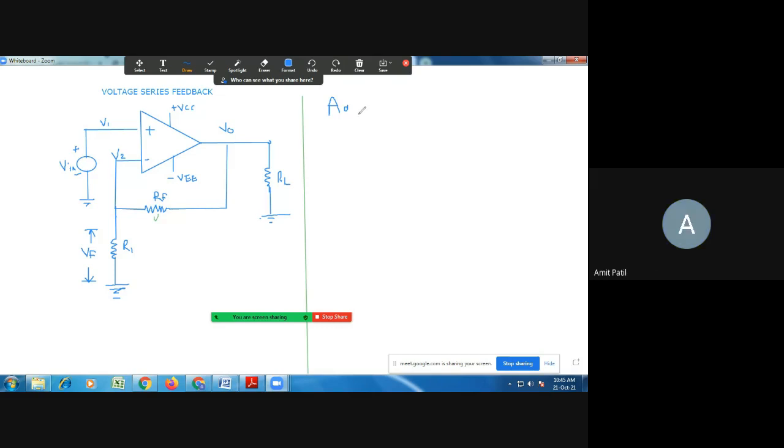Yes. Okay. So the gain is always the output. If it's a voltage gain, it's the ratio of output voltage upon input voltage. The input voltage in the case of a differential amplifier is nothing but the differential voltage, so I'll write this Vi as Vd. The input voltage is nothing but the difference voltage. Where you have a difference voltage, we always measure it between these two terminals.